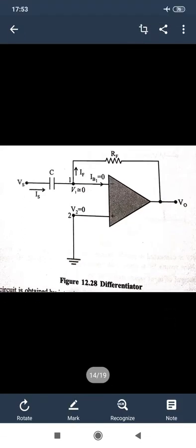Due to the high input impedance of the op-amp, the current Ib1 is nearly equal to 0. The total current is the sum: Ib1 is equal to Is plus If. When we put in the values, Ib1 is equal to 0, so Is is equal to If. Basically, the source current is the feedback current flowing across the resistance Rf, and we calculate the output according to it.